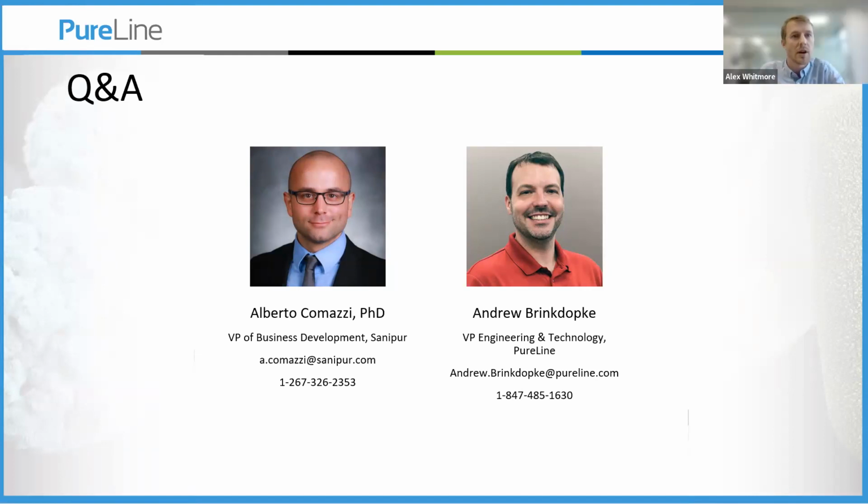Great, thanks, Andrew. Alberto, do you want to answer that for the monochloramine generator? Yeah, sure. For monochloramine generators, there are no exhaust or ventilation requirements, just because the monochloramine is generated within the water stream. So there is never a point in time where a highly concentrated monochloramine solution is being stored where the generator is. It's basically being generated at drinking water levels.